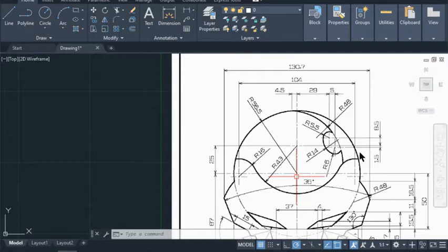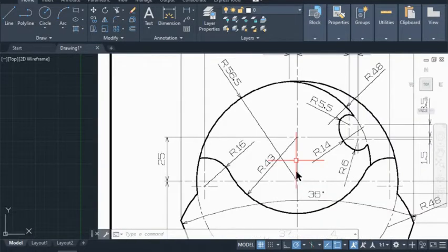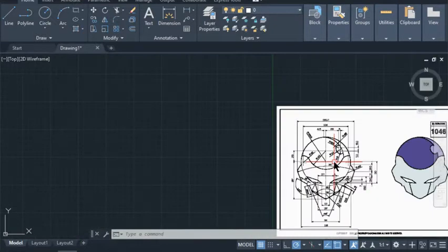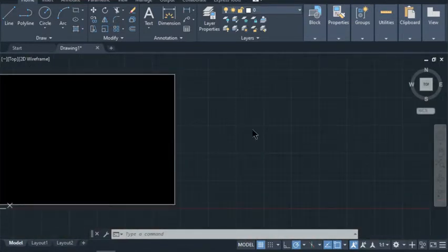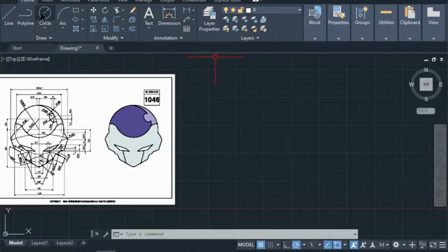All right. And then after that, we're going to see that from that center for the 56.5, if we offset it up 25 units to the top, we can use that to construct another circle, and that will be the center for this 43 radius circle. So we're going to construct those two first. All right, so let's take a look at that right here on this right-hand side. I'm going to go ahead and do that.